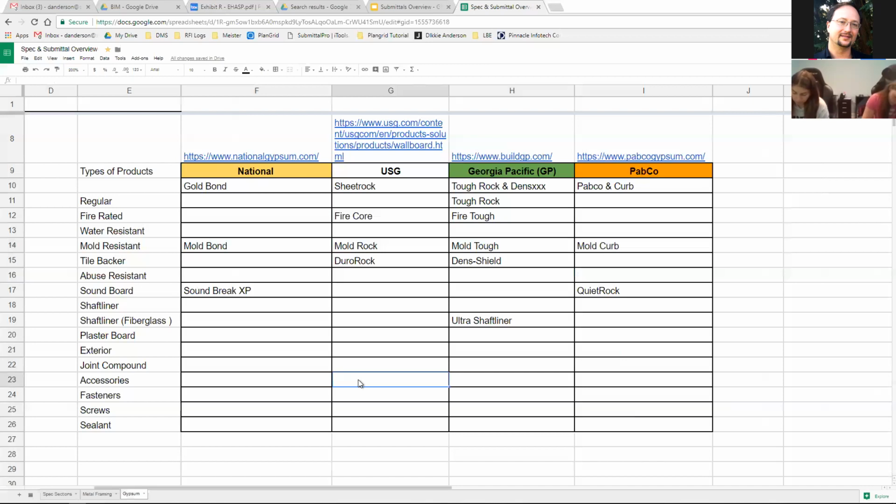For metal framing, we always use Wafer head Tek number 10s that are 1.5 inches long. And for drywall screws, we always use phosphate Bugle head 1 5/8 or 2.5 inch long screws, depending on if we're going through 2 layers.